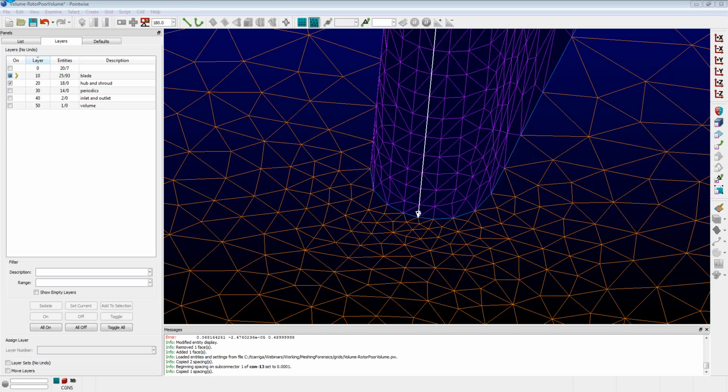We're being asked what considerations regarding mesh quality verification should one make when scripting mesh generation for optimization runs. Is creating a complex base mesh and then just changing geometrical parameters using Glyph to create various mesh instances a good idea? Is the scripted optimization of domains and blocks viable? And it is. I would say the thing that you need to keep in mind when you're writing a Glyph script to create a parameterized mesh that's going to change is just basically what type of mesh are you creating? Are you creating a structured mesh, an unstructured mesh, a hybrid mesh, a T-Rex?